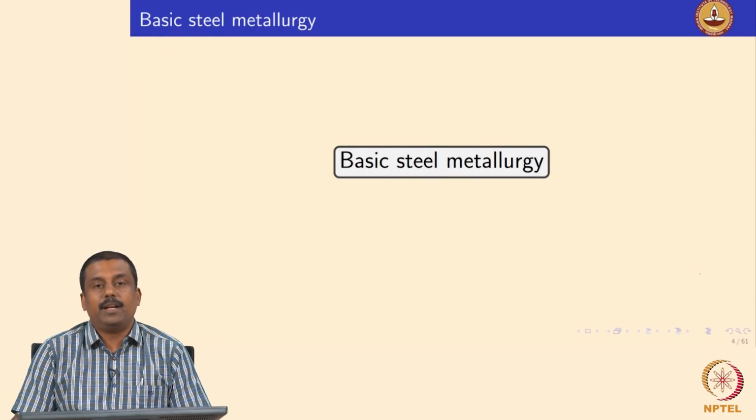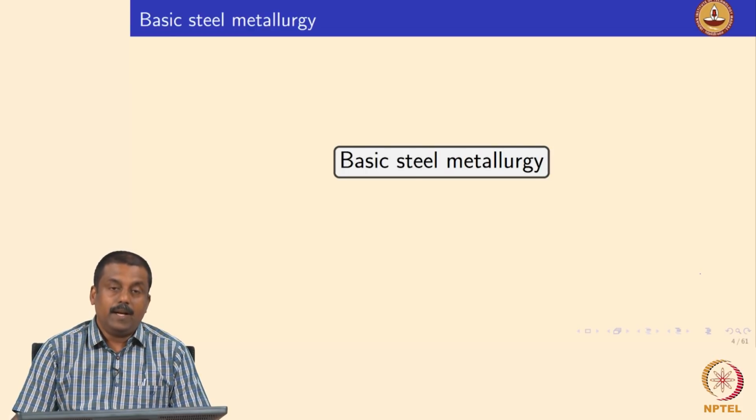So steel, you all know, is an alloy of iron and carbon. Okay, so we add carbon into iron. Apart from carbon, we also add other alloying elements. Various alloying elements are possible. The most common are manganese, silicon, chromium, nickel, and other alloying elements which are added to improve various mechanical performances, like niobium, titanium, vanadium. These are all micro alloying additions to cause precipitates, or some special alloying elements. Sometimes we even add boron.